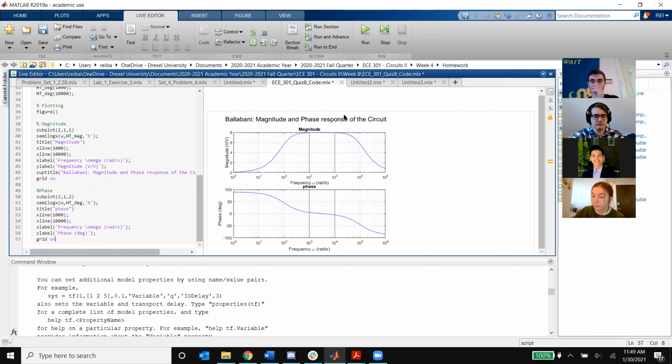Now we're going to show the short way. This is called a bode plot. So basically, as I explained before, these are the low frequencies here from 1 to 100, and these are the high frequencies here. And as I said, what we created in the circuit does not allow low frequencies to pass, and it does not allow high frequencies to pass.